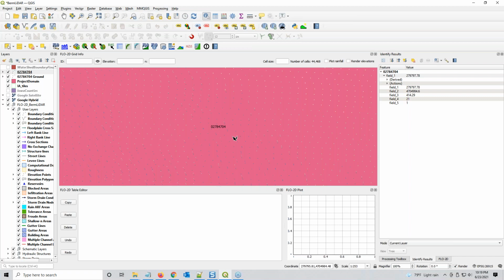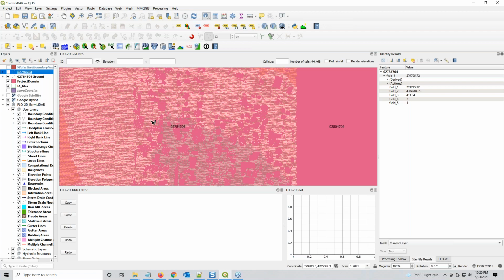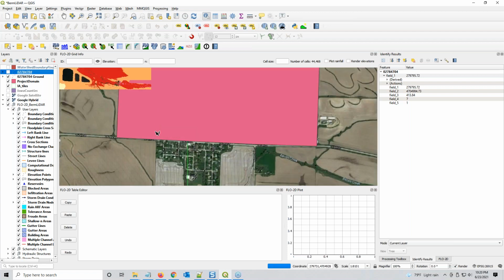So it looks to me that anything that's not ground or overlap, I think 12 was overlap, is just categorized as 1. Okay, now check it out. When we take off that, you can see that it filtered it out, and it took the buildings out, and it took the trees out. And so this data will just be filled in from its neighbors when it gets interpolated to the grid. It'll just be like a nearest neighbor type of thing.